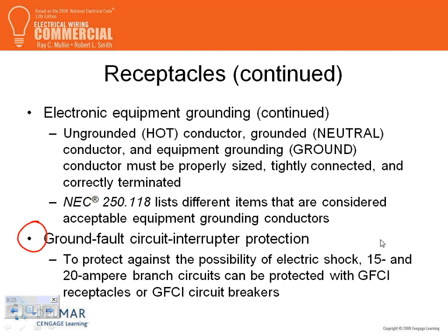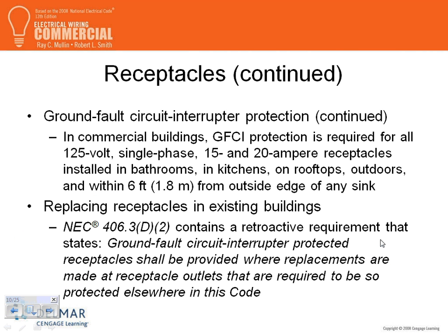In a commercial building, there are places where you need a GFCI on a 15 amp. Remember, we're not talking about residential. Residential, we know it. But in a commercial building, if you have a sink, if you have an outside receptacle, if you have a bathroom, all these wet locations have to be GFCI protected, any receptacles that you have. So keep in mind, 2 ways of GFCI, Brad, as you know: either receptacle or circuit breaker. That's basically what I want to emphasize in that particular slide.